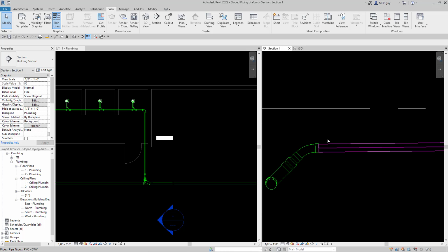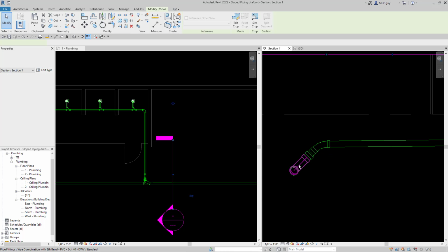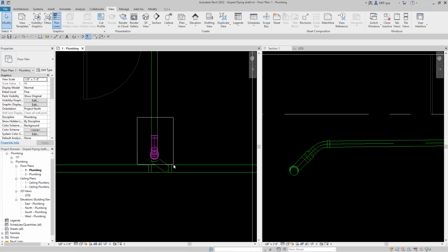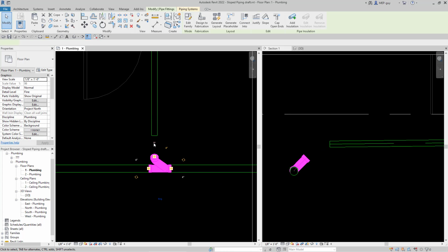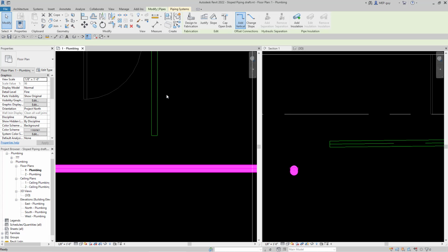So all I need to do is basically bring all of my piping to this point right here. We need to draw that first. Again, we're going to delete our pieces of pipe from this, so we're just going to delete that piece right there. For this guy, we're going to select it and hit the minus button. Then we right click on this piece of pipe, create similar.